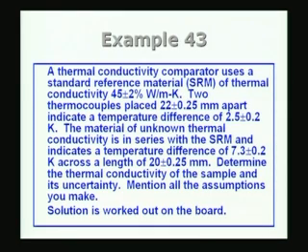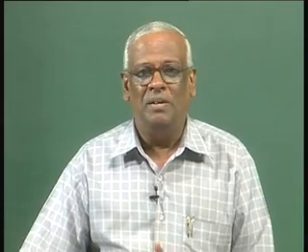In fact, in this case, the contact between the two of them need not be very perfect, because we are not measuring the overall heat transfer itself. The temperature difference is measured, the heat transfer itself we need not measure, therefore, heat transfer rate is not measured. We are measuring only the temperature differences and the length. So, that is why it is a very interesting method, because the heat transfer itself is not measured, only the ratios are required. Delta Ta, delta Tb, La, Lb, these are the ratios. In fact, any comparator for any property measurement will involve only the ratios. That is the basic idea.